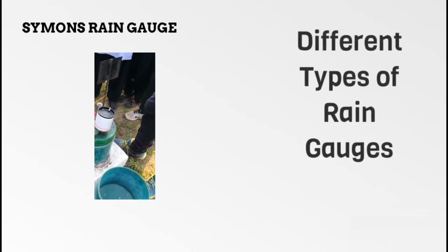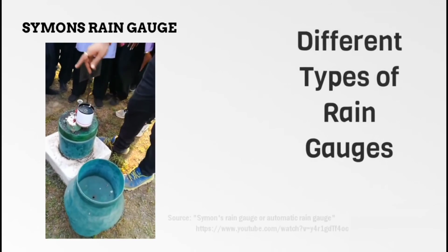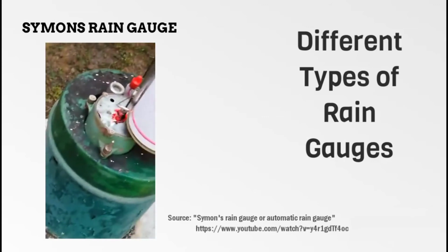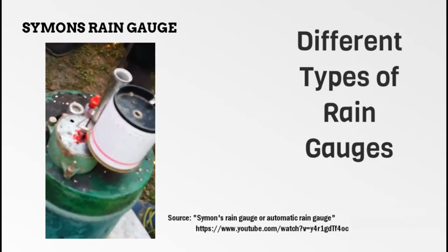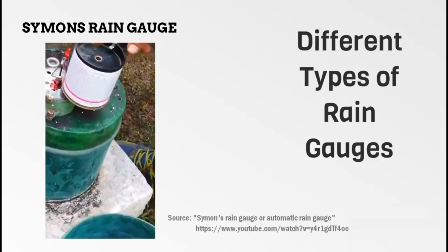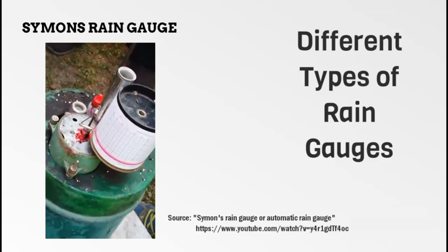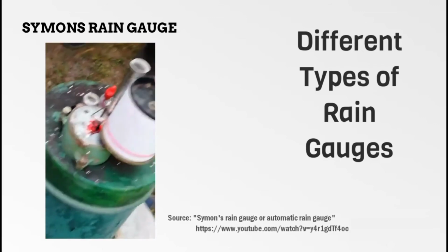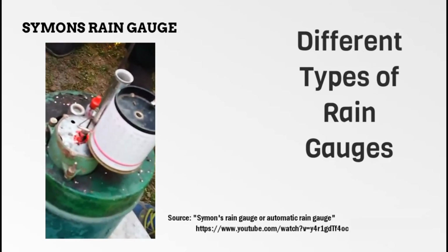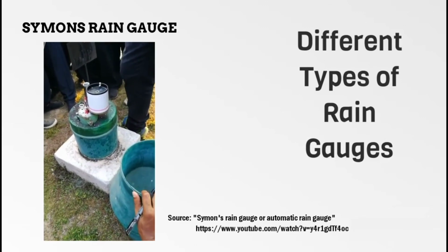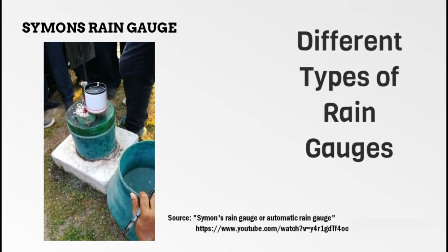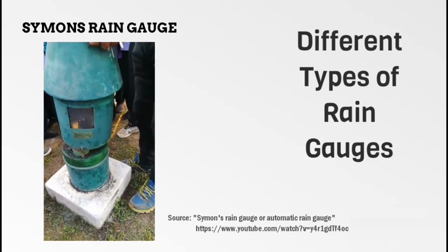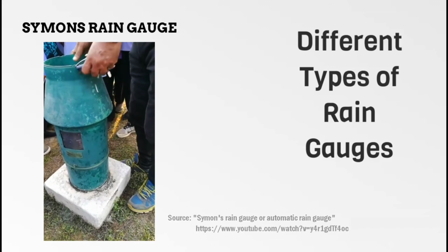This funnel shank is inserted in the neck of a receiving bottle which is 75 to 100 mm high from the base section and thinner than the cylinder that is placed into it to receive rainfall. A receiving bottle has a capacity of 100 mm, and during heavy rainfall the amount of rain is frequently exceeded, so the reading should be measured 3 to 4 times in a day. Water contained in this receiving bottle is measured by a graduated measuring glass with an accuracy up to 0.1 mm.